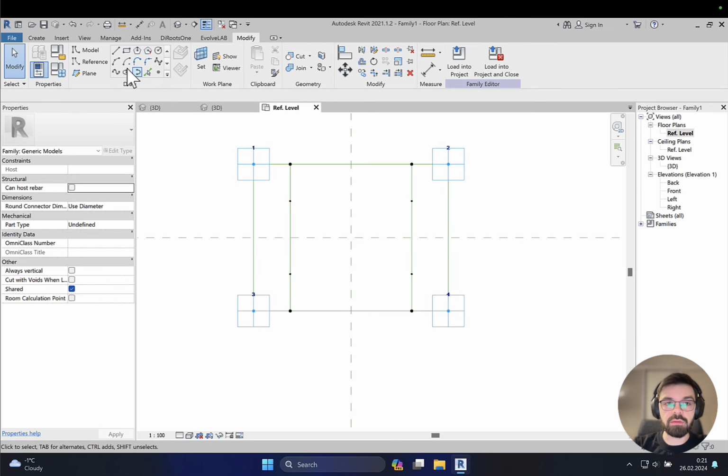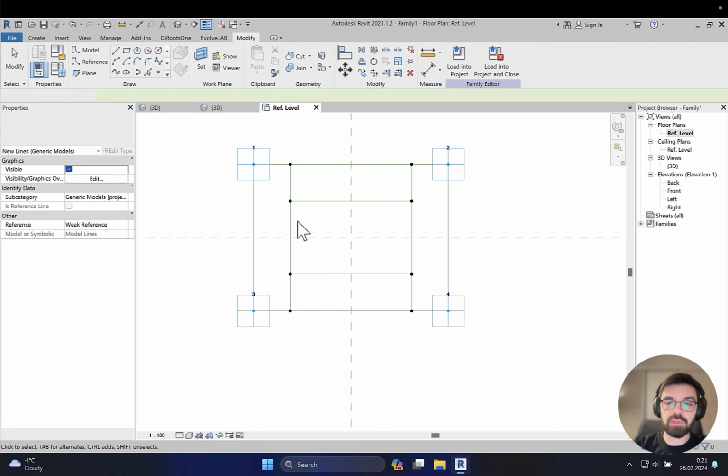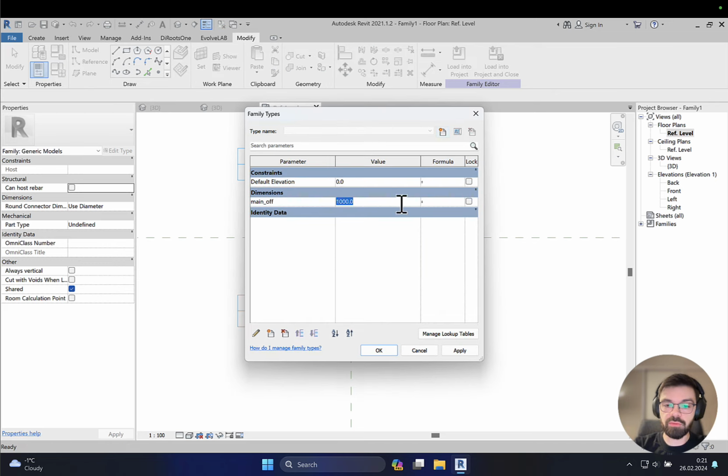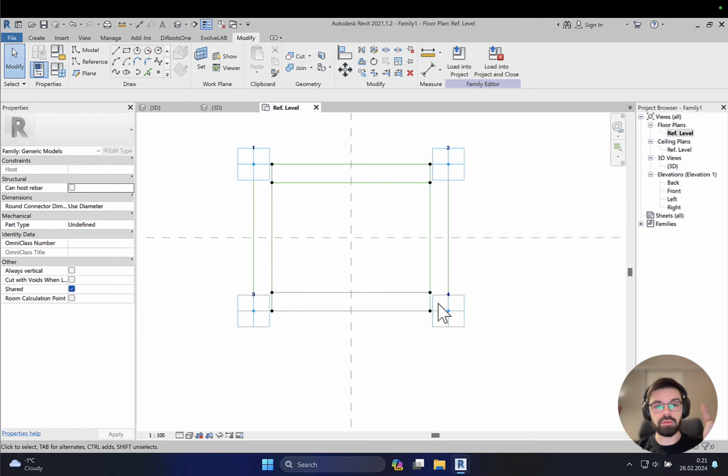Let's do the same thing here. So, what we get actually, let's go to the reference line and let's create some more support lines, one here and one here. Actually right now we get our offset 1000 mm. Now we can change it, for example, to 500 mm. Let me do it. And now you can see exactly this dot, this one, and this, creating us a really awesome offset. Yeah, by this way you can create the offset.